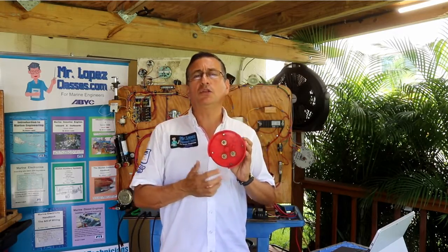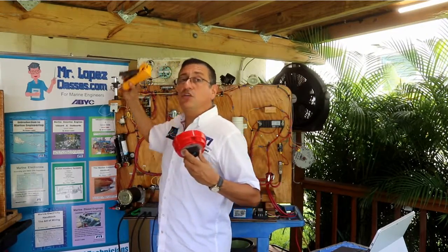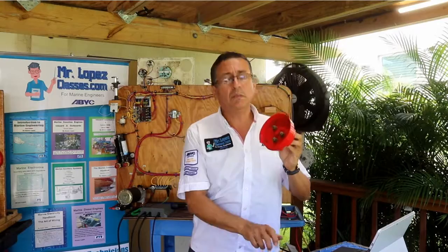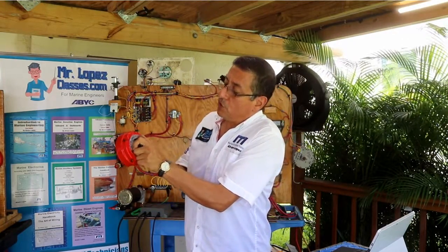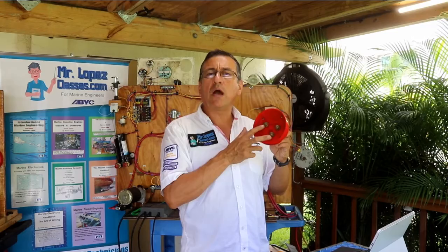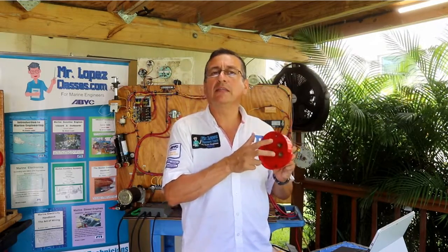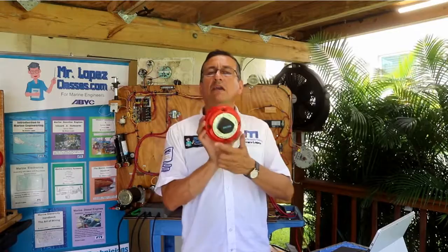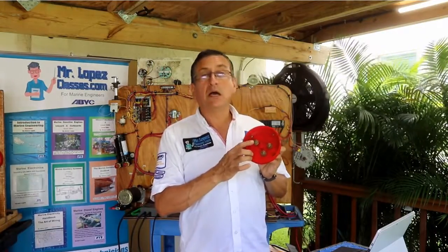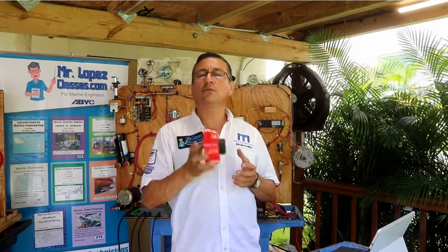What is the procedure to test my battery switch selector? It is simple. The only thing you need to check is continuity. You check continuity with your multimeter between position 1 and common. You select position 1, and it should have continuity between position 1 and common. Beep, or no beep. And now I select position 2. Beep. Okay, this is the procedure to verify if the switch is working or not working. It is the continuity between the position and the output. That's simple. That's the procedure to verify.